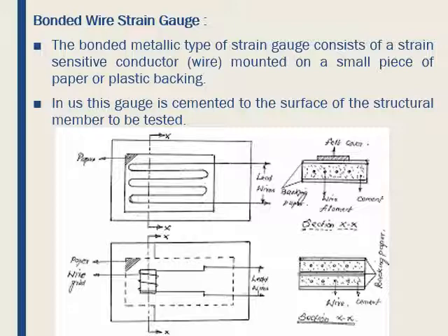However, in the foil gauges, the thickened end reduces the cross sensitivity effect to virtually zero. If the direction of principal strain is not known, then a cluster of 3 or more strain gauges is used, which are called rosettes.